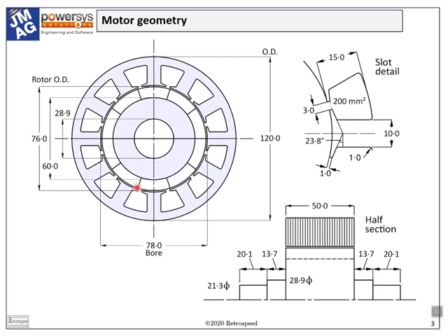Here we're going to use 10 poles, but the same stator core, rotor hub, and shaft could also be used with 8 or 14 poles. Even the same coils wound around single teeth could be used, but the interconnections could not be reused, and that is what we're going to start with.